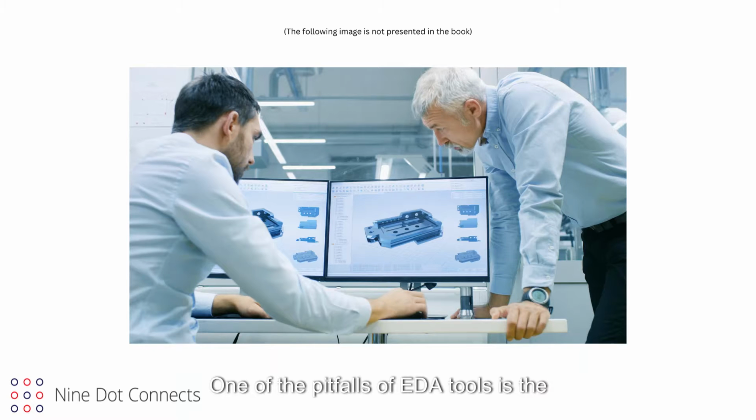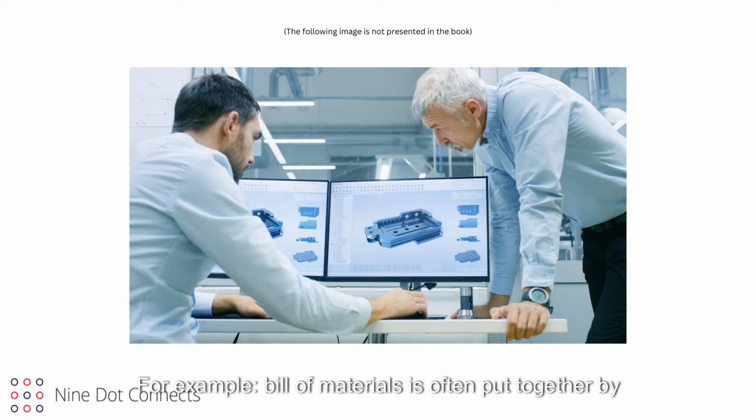One of the pitfalls of EDA tools is the reliance upon a push-button solution to generate the manufacturing documentation. We need to understand what documentation is needed, what is in the documentation, and more importantly, what is missing in the documentation. For example, the bill of materials is often put together by hand because the libraries are not properly formatted. Schematics are difficult to read because net names are not applied, or details are not explicitly noted. Assembly and fabrication notes that give specific instructions are often missing. Knowledge of what documentation is needed is as important as the documentation itself. And, most importantly, it is the understanding of how your document package gets formed. Therefore, understanding the project flow is critical.